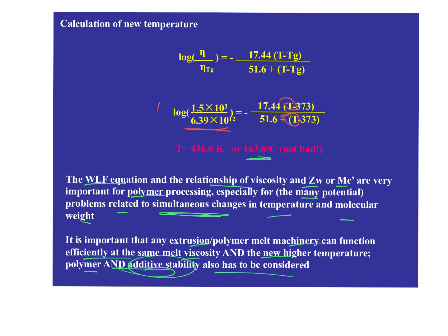Are you more concerned with the additives like pH rising or like evaporating out? I'd be concerned with the additives no longer functioning at those higher temperatures. I'd be concerned about the color becoming something else at higher temperatures because they're only rated to a specific extrusion temperature. You go above that, then they start to oxidize or break down or cross-link. All kinds of things can happen. Any other questions?